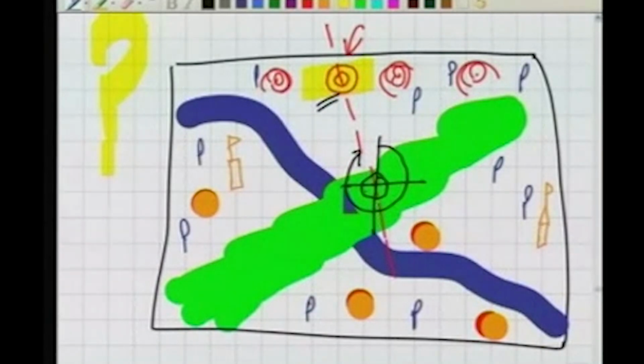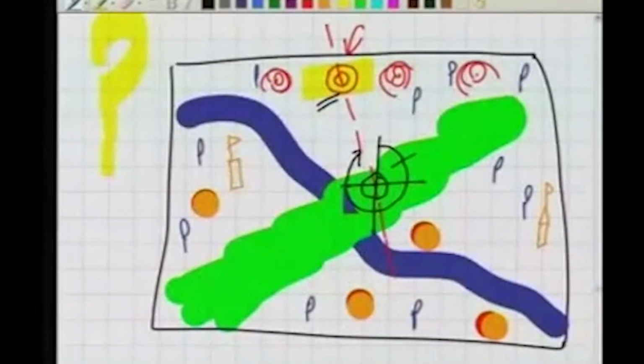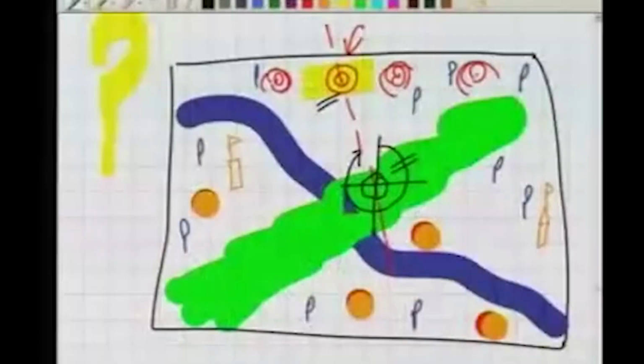Once we know this fore bearing, next our job will be using this prismatic compass, because in the case of the prismatic compass, while I am seeing through the prism, I can see the graduations, the observations, as well as I can sight the object. So I keep rotating till the reading here is equal to this fore bearing value. Once it is so, I am sure now, well, this particular tower is in this line of sight. So out of those 10 towers, whichever is in this line of sight will ensure that yes, that is the tower in which we are interested.